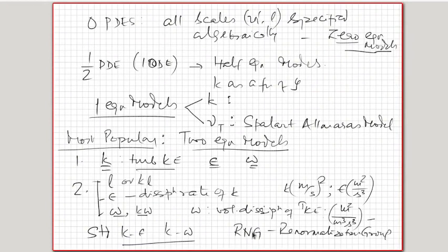So there is a renormalization group theory in turbulence which basically captures how when the flow goes from a high speed region to a relatively lower speed region, it regains some level of laminarity, which basically means that the nu t decreases as you go into the lower velocity regimes. So that is the RNG, or sometimes called the realizable. So RNG and realizable k-epsilons are variants of the standard k-epsilon model.